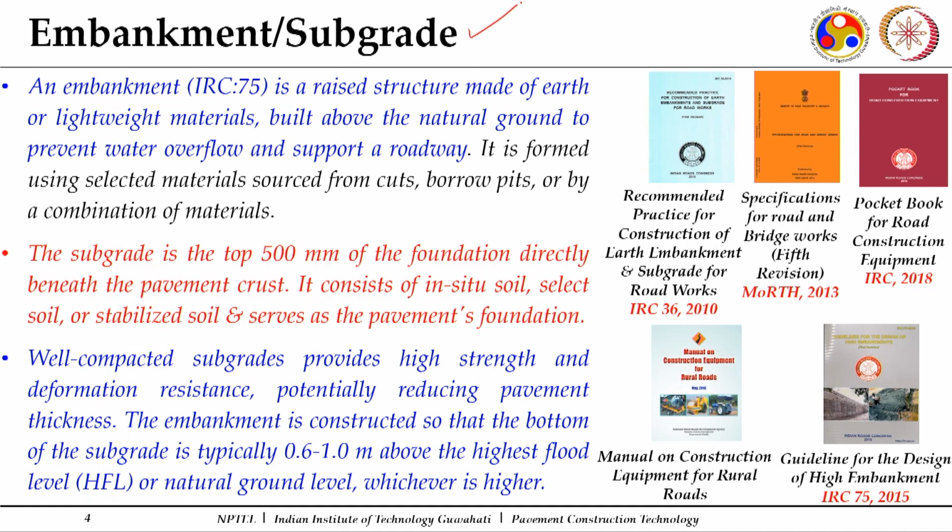When it comes to both embankment and subgrade, these are the layers which are usually constructed using the in situ soil or soil from a nearby borrow area, and in certain cases, if the soil is quite unsuitable, some stabilization may be required for making use of it in subgrade and embankment construction. Certain industrial waste, for example fly ash, is also used specifically for the construction of embankment.